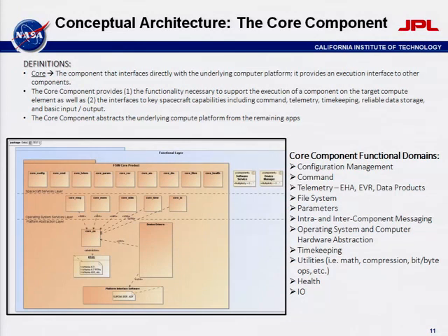And then at the top layer of the core component, and at the top layer of this functional layer, where the software services and data device managers also live, is your spacecraft services layer. This is a set of services that the core team determined are pretty much common from mission to mission. So this is command, telemetry, parameter management, health services. These are things that we see from mission to mission are pretty standard, pretty common, and so we're putting them internal to the flight software core to provide for a particular mission.